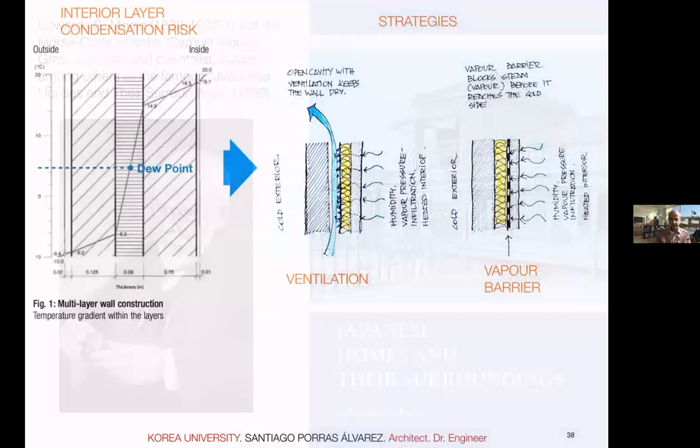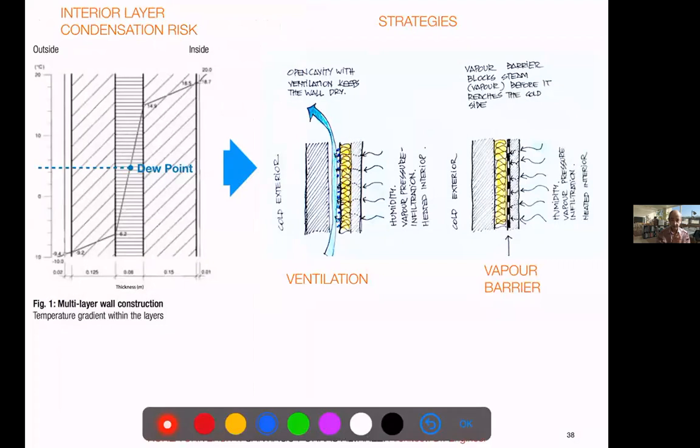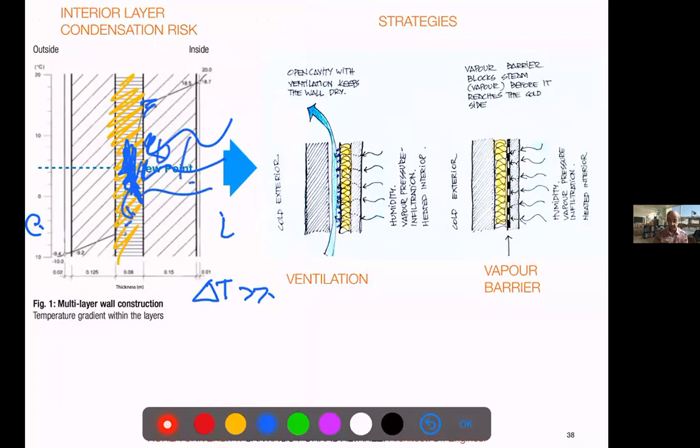For the multi-layer, there is something that you surely studied in other courses, but we have to repeat. Since we have a strong insulation layer, we have a big temperature difference, right, between interior and exterior. You might have points where you condense water, where the vapor inside gets cool enough to wet the insulation of the inner walls, and that's a problem.